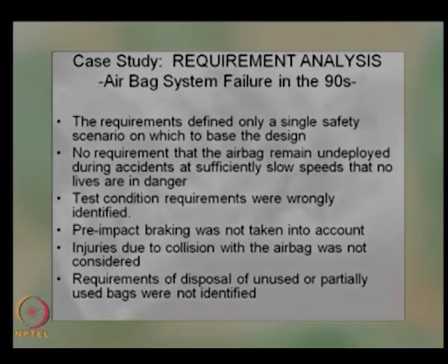So when the airbag is deployed and the driver is moving forward because of the impact, there was a possibility for the driver to get injured because of the airbag. The sufficient elasticity of the airbag or the pressure to be maintained, all those things were not considered when the airbag was developed. And another one was the requirements of disposal of unused or partially used bags were not identified.